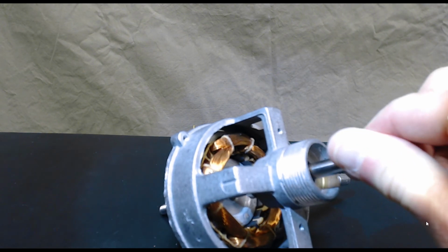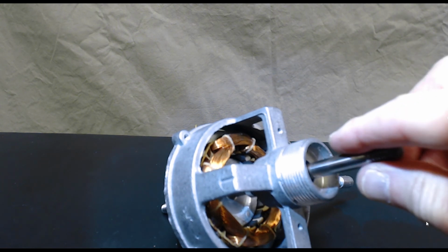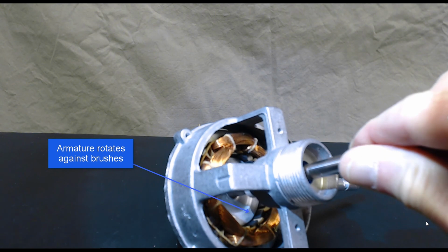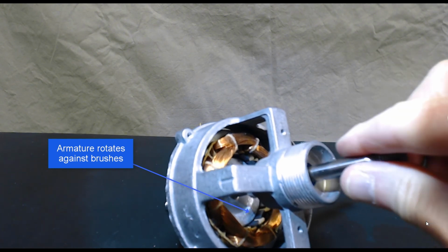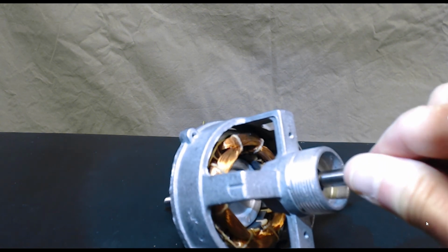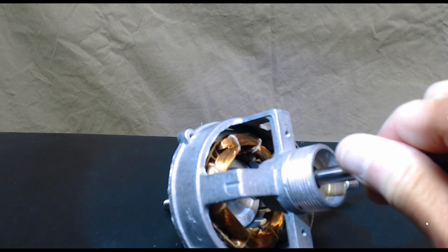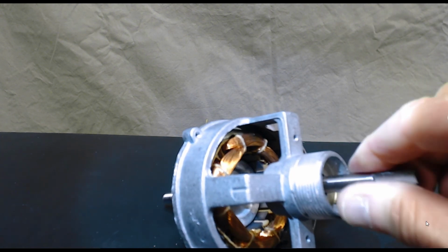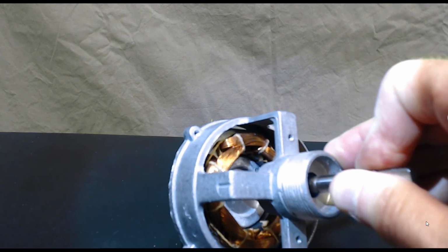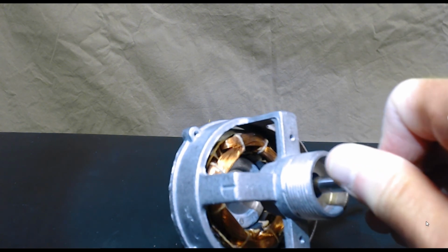And I rotate the armature and you can see just how close this armature really is to those carbon brushes as it rotates around. I think I said before you got to have about 20 thousandths clearance max. This one probably has about 1 or 2 thousandths clearance because I can feel the armature dragging on the brush as it rotates, and I can actually hear a sound of it. Maybe you can hear it too in this video as it rotates on the brush.